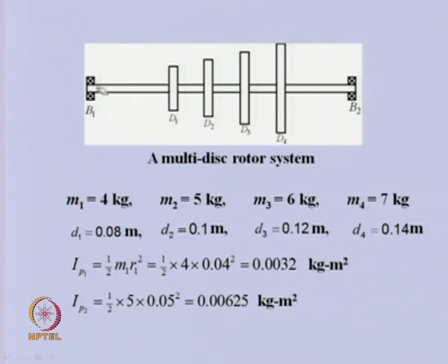of the shaft. So, the shaft segment which is here and this end, during torsional oscillation will be moving along with this disc, and this will move along with this, as a rigid body. So, as such they will not contribute to the torsional vibration of the system, because they will not get twisted, because there is no inertia attached to this. So, only these segments will be of relevance.